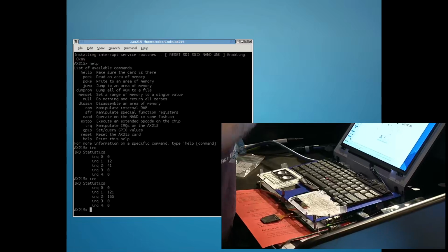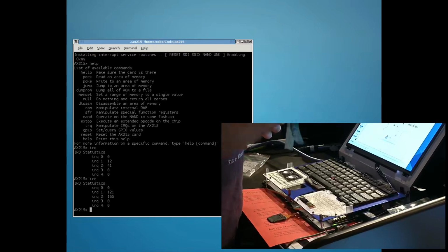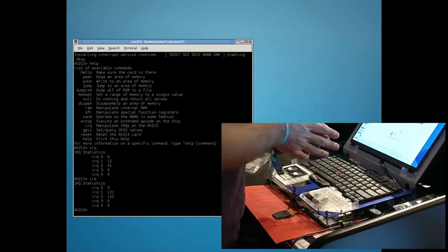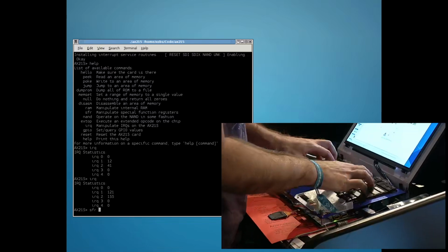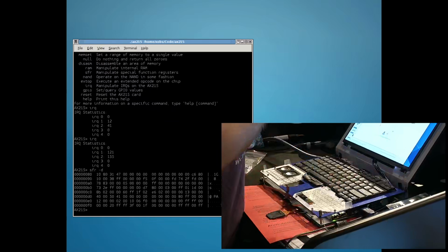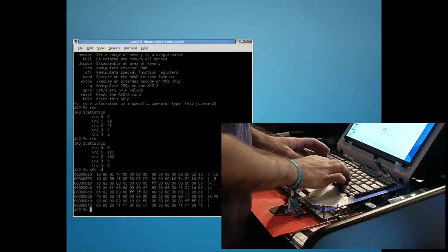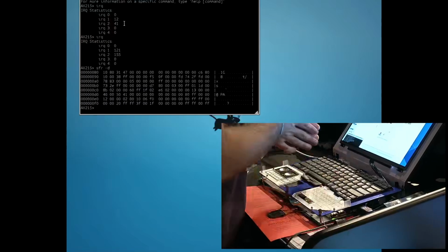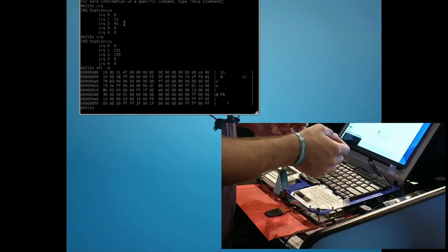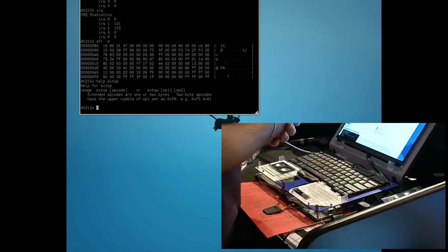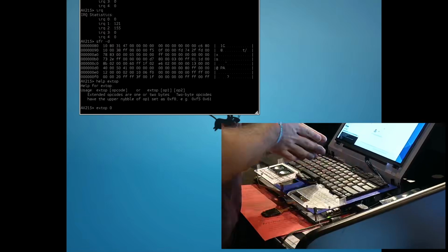Yeah. Because these numbers keep going up, it means IRQs 1 and 2 probably have to do with the SD communication. Other things we could do is dump the special function registers. One of the nice things about 8051 code is that there are only 128 possible registers. Makes it really easy to fuzz. What else? There's also an external opcode command. I mentioned this in the talk, where you can have it execute an arbitrary opcode. So we'll send it A5 and then 1D.